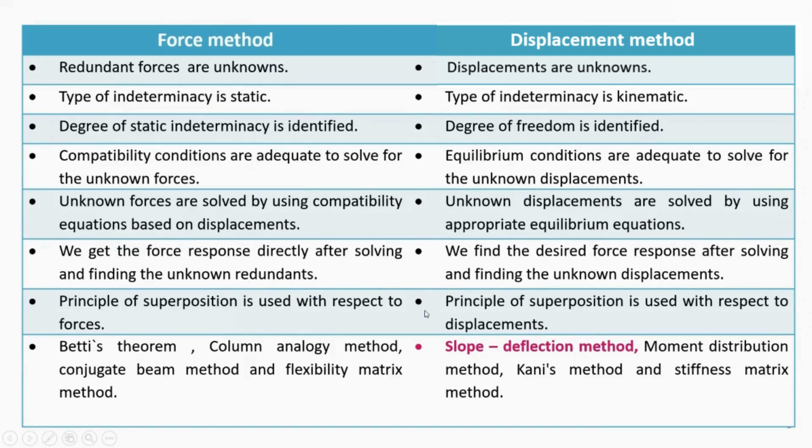In both these methods, you are going to use the principle of superposition. In force method, it is used with respect to the forces, whereas in the displacement method, it is used with respect to the displacements. Some of the methods related to the force method are Betti's theorem, column analogy method, conjugate beam method, and flexibility method. Whereas the methods related to displacement method are slope deflection method, moment distribution method, Kani's method, and stiffness matrix method.